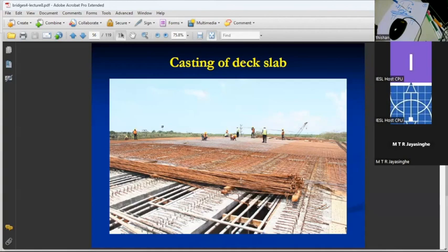But most of the other highway loading may not be that significant. And also, even in that case, you need a kind of traffic jam on one side of the deck, because these are 4-lane decks. So on one side, 2 lanes are full of traffic, other side is empty. So that type of situation would be needed.